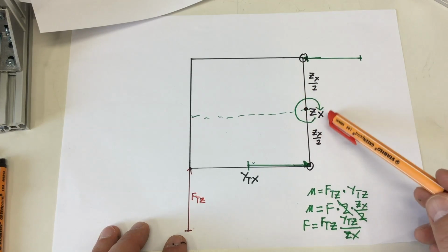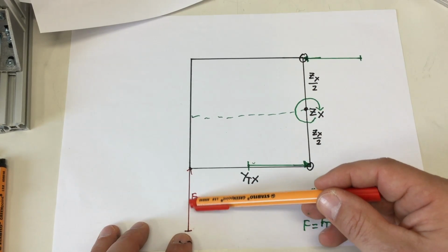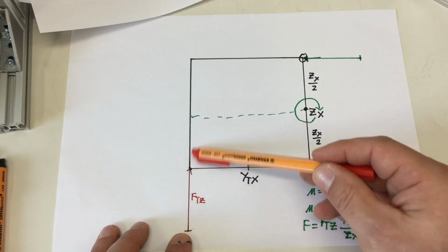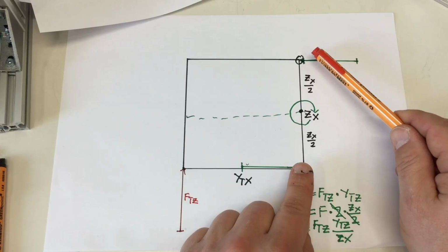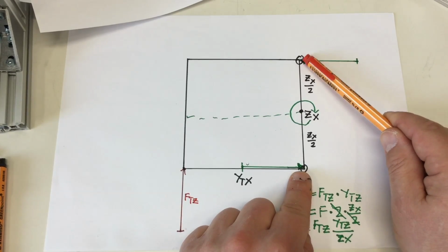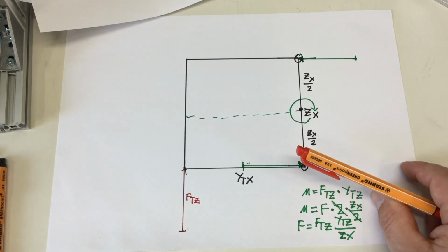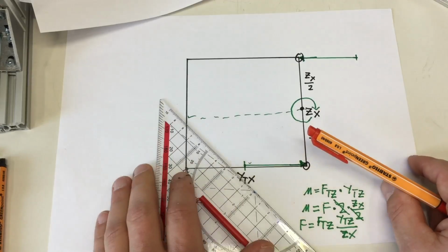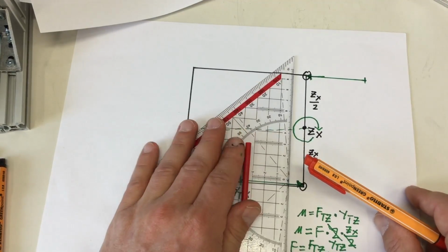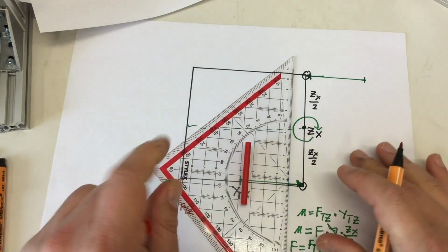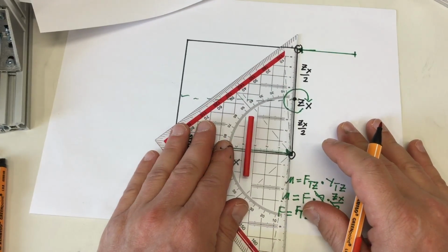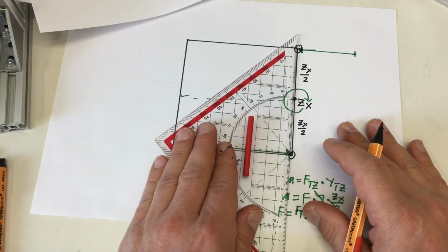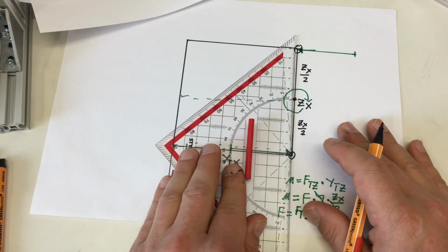So we handled the momentum, now we still have a resulting linear force going upward. And since we have two bearings, and now, attention, shortcut, we need two forces of the length of half that length, 2.5, going downwards.